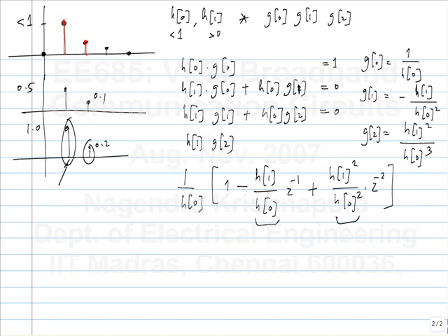Because this is the one that's contributing to the desired symbol, that's the contribution from the desired symbol, and rest of these are the contributions from the intersymbol interference. So if the ratio of these two is a constant, the amount of intersymbol interference is a constant. And to that you need to have a gain of 1 over H of 0 so that you can restore the amplitude of the cursor to the same level as before. This is to overcome the sensitivity of the slicer.